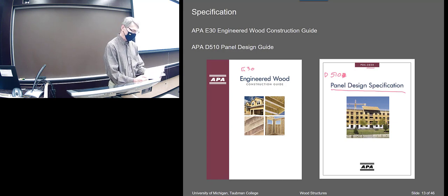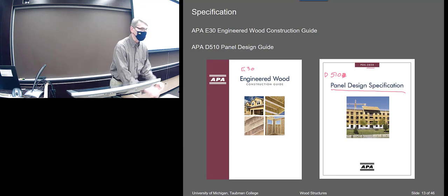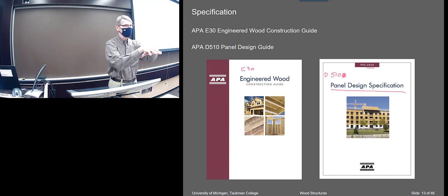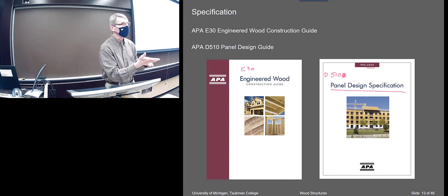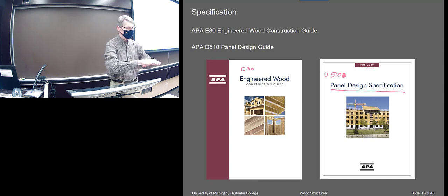It has the tables that actually give strength. So these are all given in terms of strength because, of course, you've got a composite. The section is not... what do you call that? It has a different E modulus in different directions. Every composite is not isotropic, it's anisotropic, I guess is what you'd say, because it has a different E modulus in the different layers as they change.